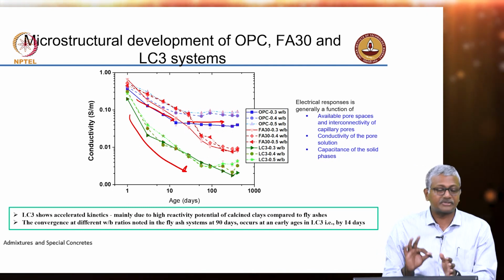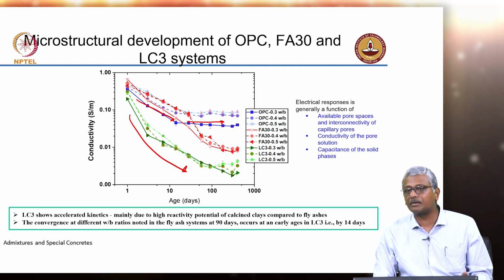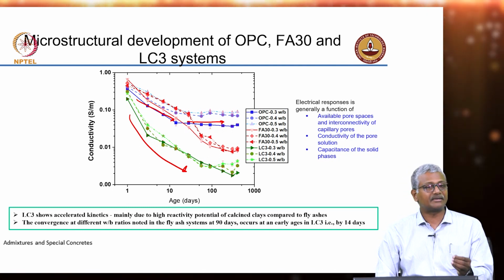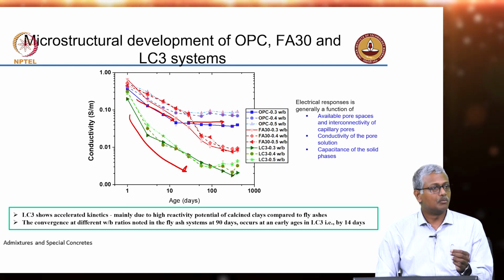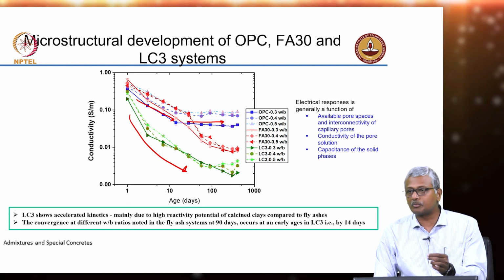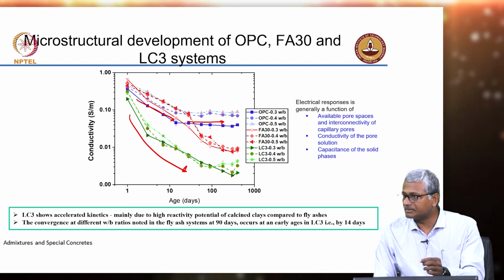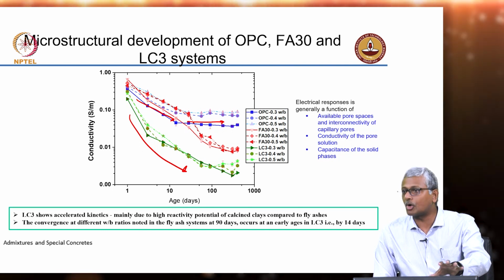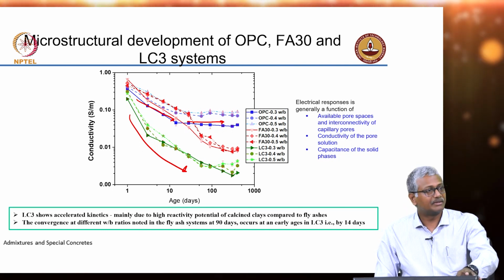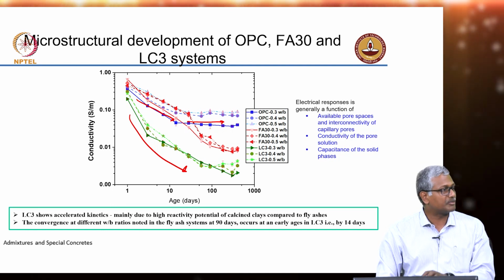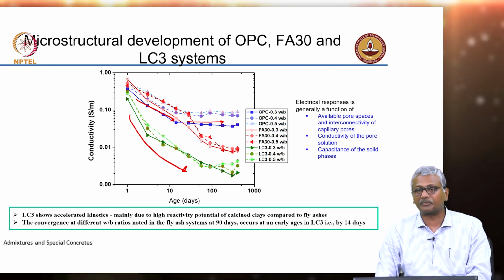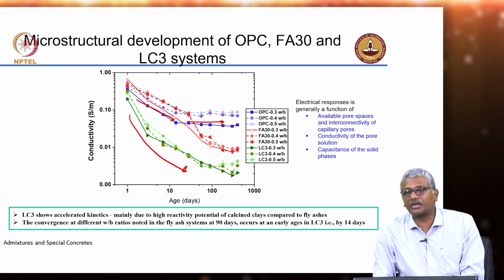Now, again, please always remember, whenever I am talking about electrical properties, there is always that aspect of ionic strength of the pore solution that always comes in. Okay. So, the result cannot be just looked at as a beneficial reduction in permeability, it could also be contributed from the reduction in ionic conductivity,